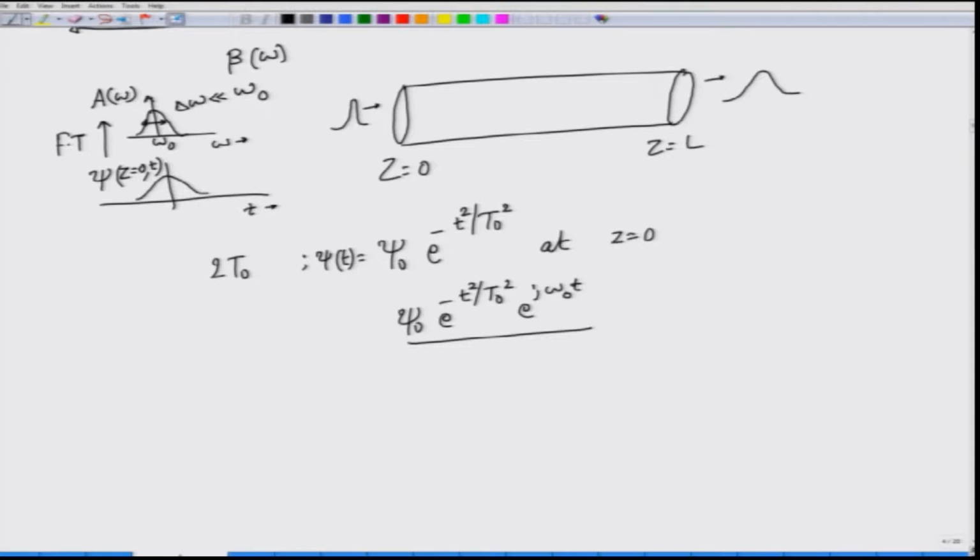But in addition to this one, there is also a transverse distribution of the pulse itself. So, that is f of x y or equivalently f of r phi, which tells you how the mode is distributed in the transverse plane, right. So, we solved an equation for how the mode would be distributed in the transverse plane. The fundamental mode in terms of r and phi depends like this: J0 of u r e to the power j nu phi, or rather for the fundamental case this will be independent of the azimuthal number phi, but this is the transverse field distribution.